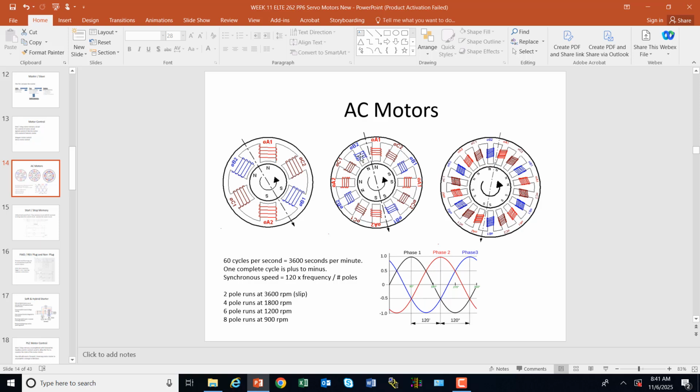So this right here is just showing 3-phase motors once again. This is 1 red, 2 red, 3 red, 4 red. So that's my 4-pole. And this is 1, 2, 3, 4, 5, 6, that's my 6-pole right there. But there's 3 phases, so everything's timed by 3. So we're talking about 60 cycles per second electricity, but there's 3 phases.